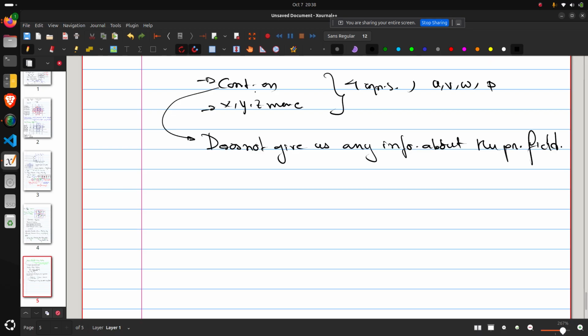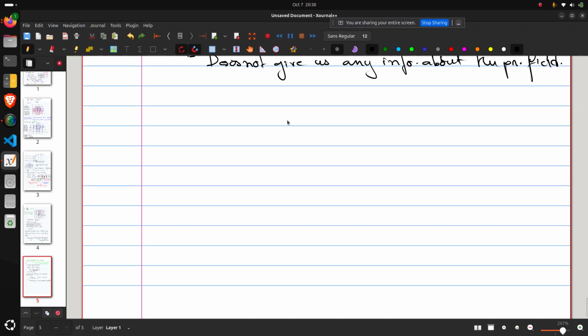From that pressure correction equation we obtain the pressure correction terms and we use them to obtain the velocity correction terms, and then we substitute the correction term in u is equal to u star plus u prime and get the actual value. Okay, now let's see how it is done.